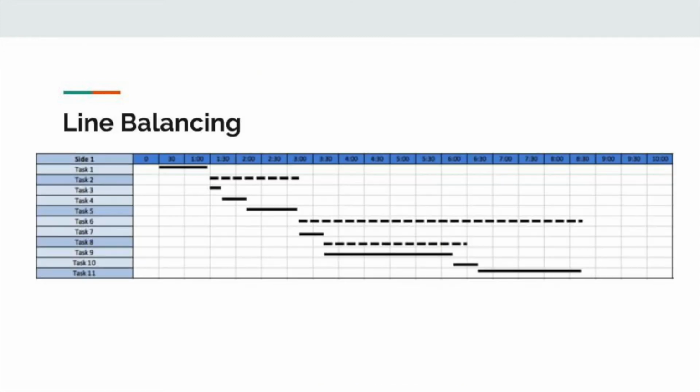Finally, we conducted a time study to find the cycle time for all tasks completed in the cell. We then validated the data we collected with standard work documents provided by the company. This is an example of a Gantt chart we created for each of the operators in the cell. It visually displays each of the tasks with its corresponding cycle time. After comparing the Gantt charts and identifying the bottleneck operator and task within the process, we decided to rearrange responsibilities across the operators to balance the workload. This allowed us to ultimately reduce labor hours in the cell while maintaining the cell throughput.